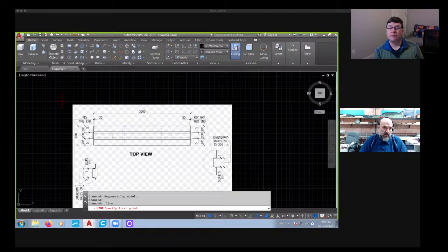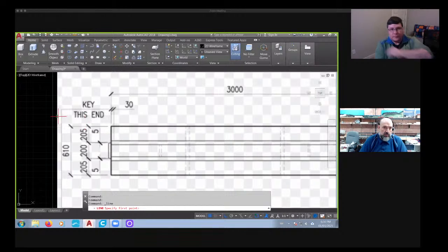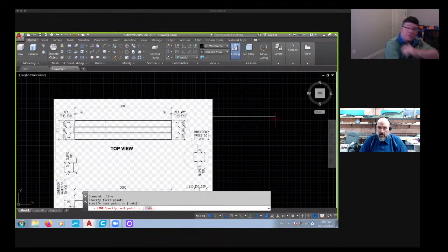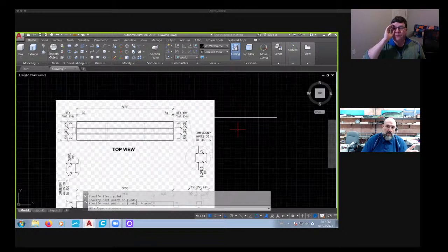So I'm going to take what's called a work line. It's just a random line you put in CAD, and from this line I can easily pull off other lines. You follow me? It's not something we actually use as part of the model. I put a work line from this side beyond the attached picture, because then I know it's straight. I do have an ortho tab on the bottom, which is on right now, but this guarantees it's straight.